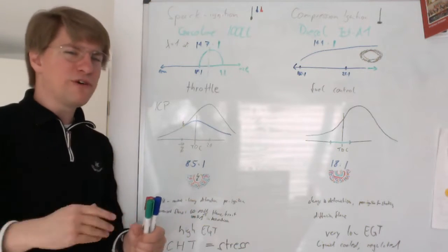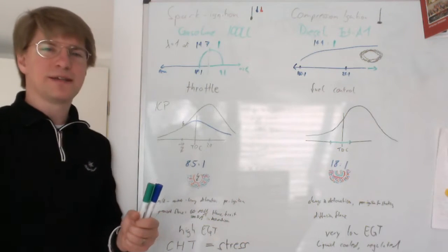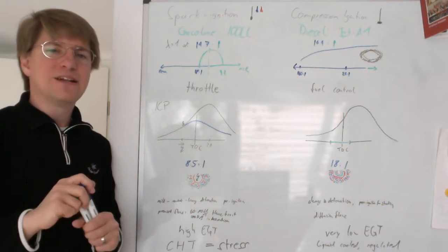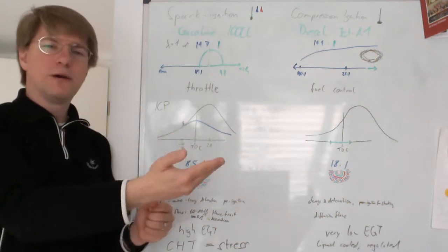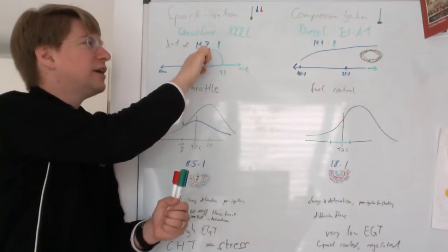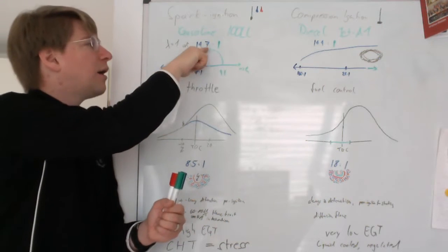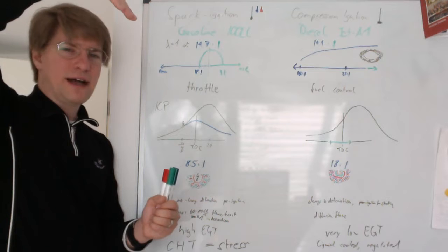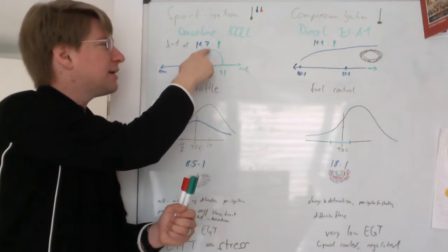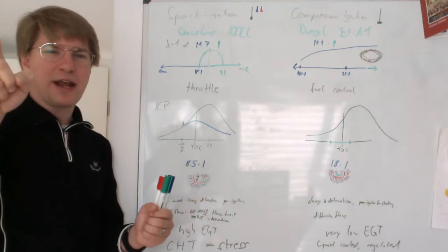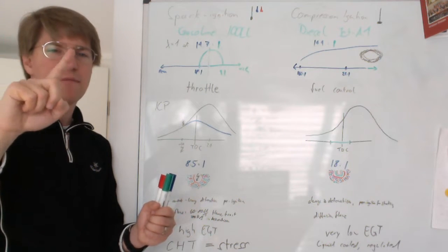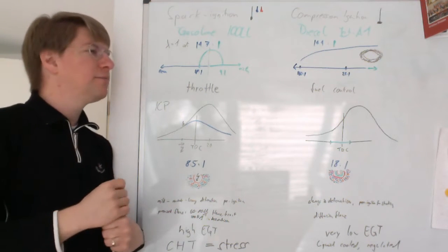So for the takeoff, you're a little bit on the rich side, and in cruise at, let's say, 10,000 feet or so, you pull back the mixture even further. You go across the peak at 14.7 to 1, at lambda equals 1. This is when your EGT needle, the EGT gauge, peaks and comes back to cooler.